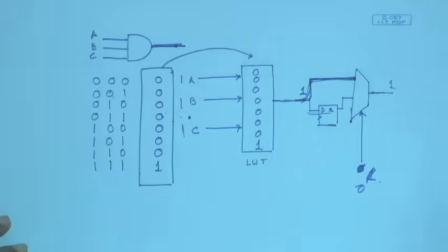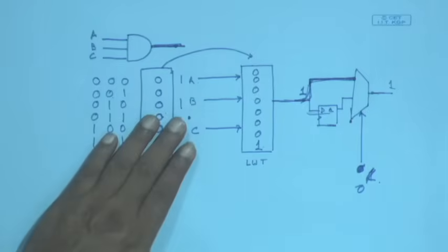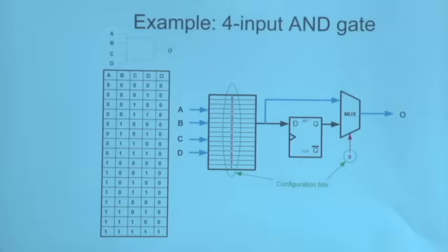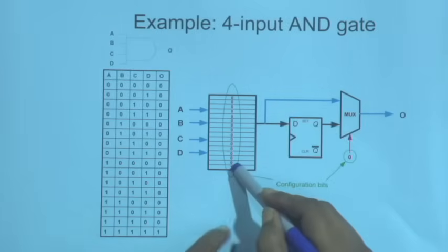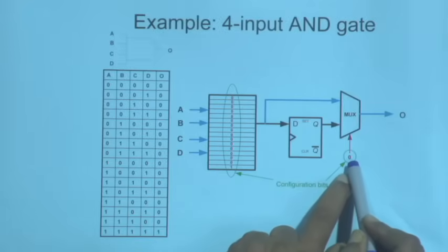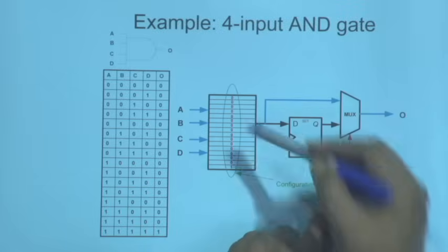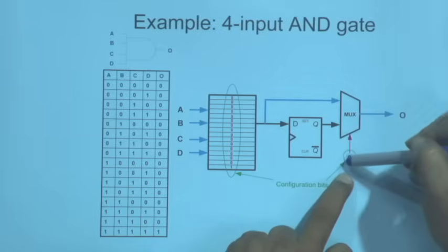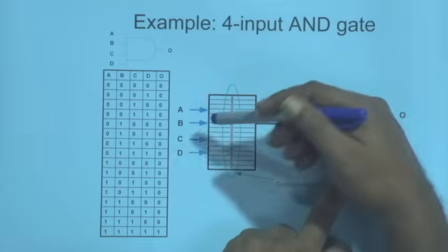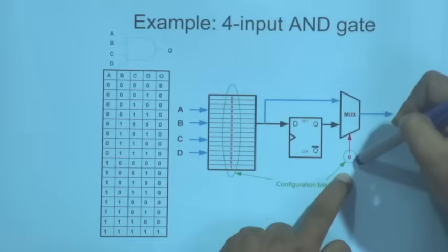clear. Therefore, in order to get the logic function implemented, what I needed is 2 parts of the programming. What are those? One is configuring the lookup table and configuring the multiplexer control, right. So, these are known as the configuration bits,